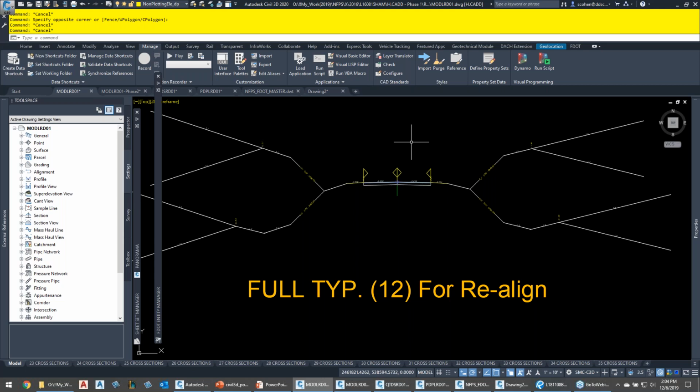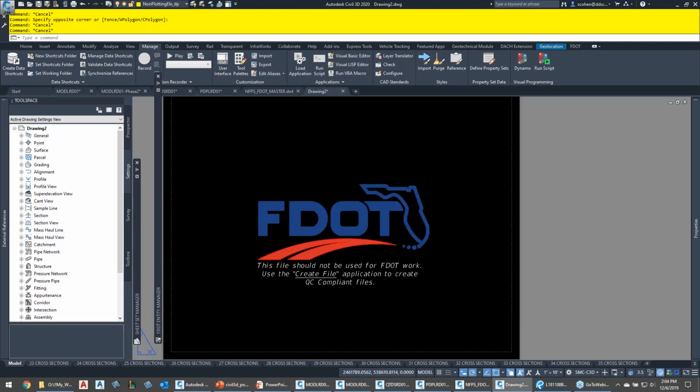By doing so, this automates your CAD standards. If you need to add a layer, a block, a line style or linetype, or a Civil 3D style, or you change a layer's properties, it updates in thousands of drawings linked to that reference template. So again, I see no reason why you would not want to use this, but let me go over the process. It's really straightforward. The first thing I'll start with is a totally blank DOT drawing.